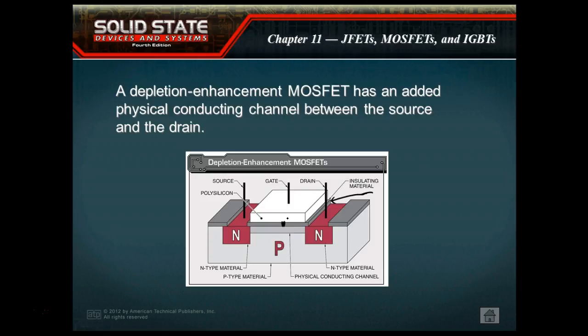And the problem is you might punch a little tiny hole through there and it doesn't show up instantly, but later on it kind of cascades. When current flows through there, it starts getting a little hot, then causes the silicon layer or the oxide layer to break down a little more, and then over time it goes bad.